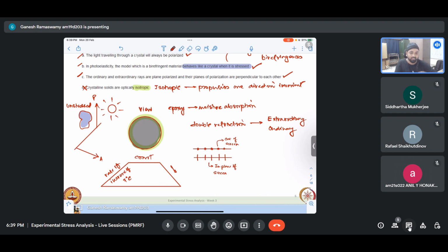Only thing is, sometimes when we do it for certain epoxies, it introduces a tint. It will become yellowish. Otherwise, when we cast epoxy, it is generally transparent, so it will acquire a yellow tint. But ideally, material properties don't get affected much by it. Even if they do, we can calibrate it using a calibration experiment.